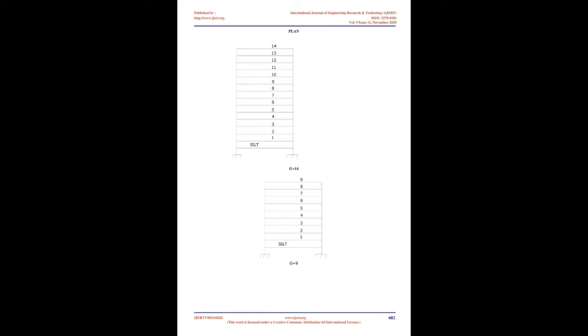Buildings and other structures are composed of horizontal and vertical structural elements that resist lateral forces. The horizontal elements, diaphragms and horizontal bracings, are used to distribute the lateral forces to vertical elements. The vertical elements that are used to transfer lateral forces to the ground are shear walls, braced frames, and moment-resisting frames. The structure must include complete lateral and vertical force-resisting systems, capable of providing adequate energy dissipation capacity to withstand the design ground motions within the prescribed limits of deformation and strength demand.